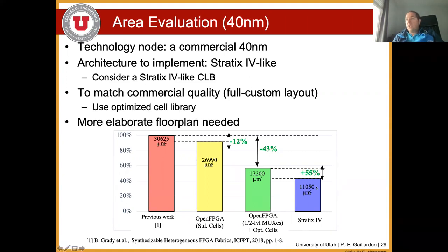What we're seeing here is that proper pre-planning and pushing the tools typically brings us to an FPGA 2x bigger compared to a commercial FPGA, which is good, but from a manufacturing perspective, the COGS would be very large in that case.